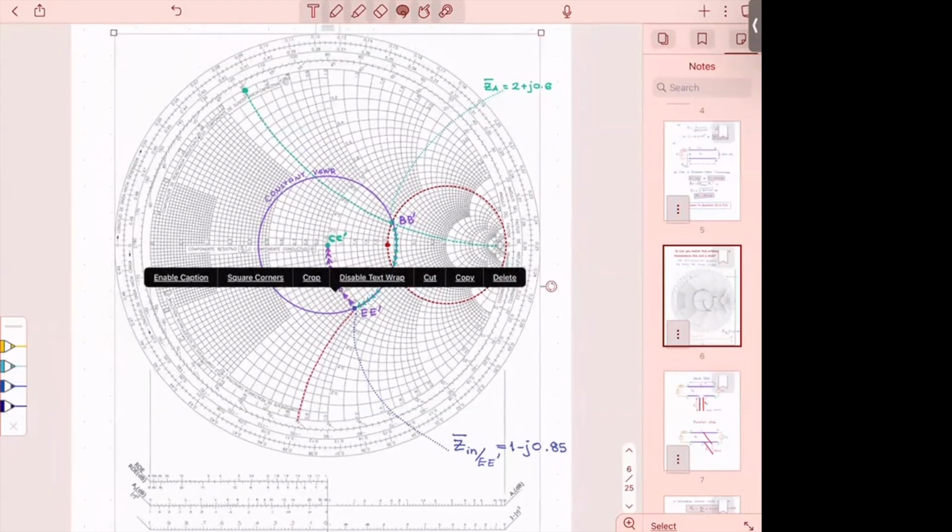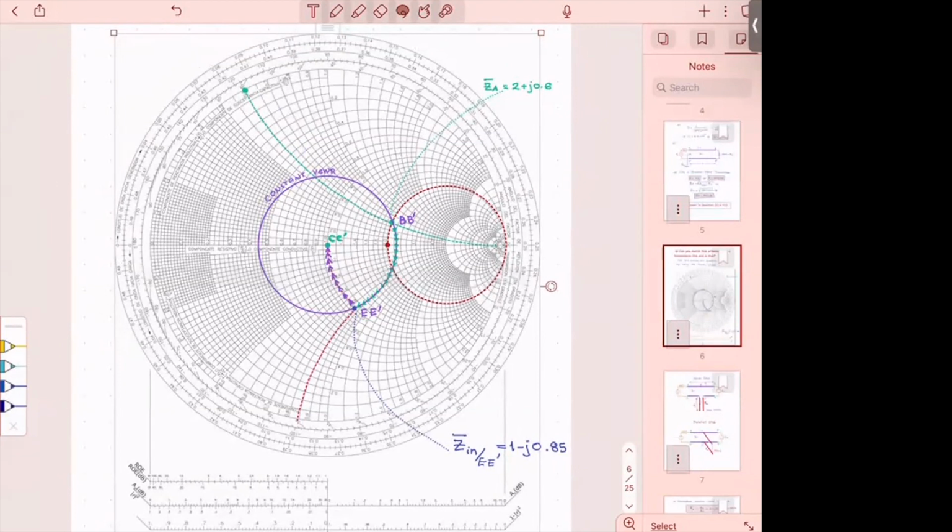Of course, in a matching network, you will never add a resistor. Why? Because you are going to lose power. You add a resistor somewhere, part of your current is going to flow through the resistor, and you lose it. Okay? So the only thing that is acceptable is to add a lumped element. But we're not going to move here since we don't do a hybrid design. So the only thing I can do, by excluding the other ways of transportation on the Smith chart, is to move around this, number one.